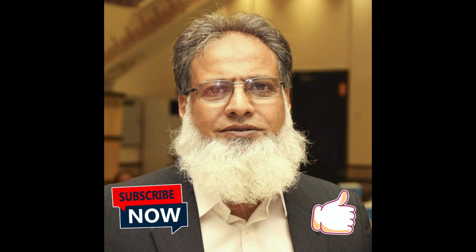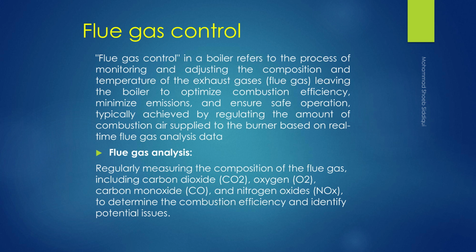This is Part 3B, continuing Part 3 in which I am discussing boiler efficiency. Flue gas control. Flue gas control in a boiler refers to the process of monitoring and adjusting the composition and temperature of the exhaust gases (flue gas) leaving the boiler to optimize combustion efficiency, minimize emissions, and ensure safe operation, typically achieved by regulating the amount of combustion air supplied to the burner based on real-time flue gas analysis data.